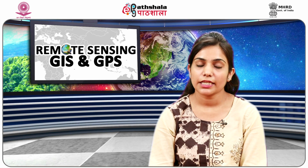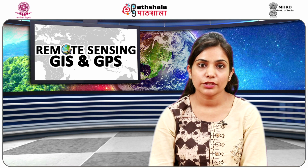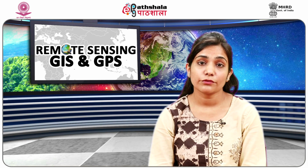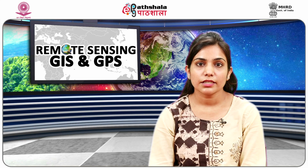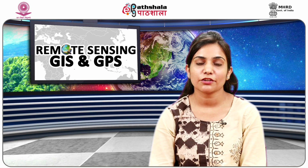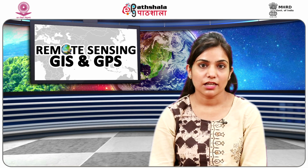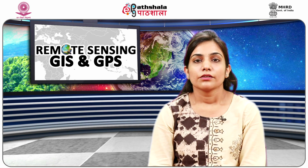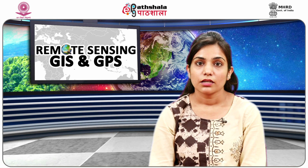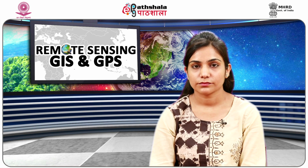Next we need a digital elevation model, and a digital image produced by scanning an aerial photograph with a precision high resolution scanner, and lastly a soft copy photogrammetric workstation for processing the imagery to derive image and vector products. A digital photogrammetric workstation combines computer software, that is a graphic workstation, with, in most but not all cases, a stereo viewing device and a 3D mouse. The software configuration includes ERDAS Imagine with Leica Photogrammetric Suite.